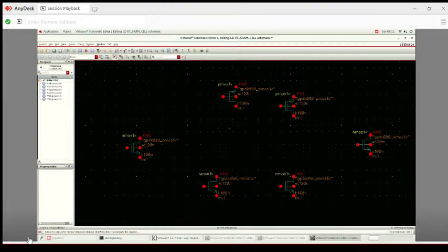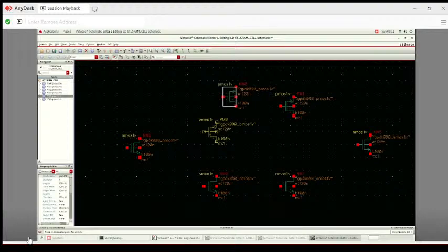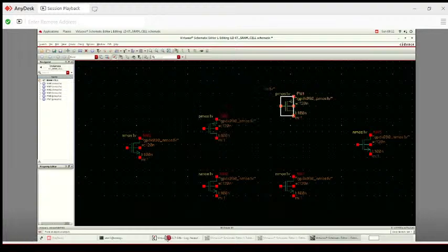So we zoomed in. As we can see, 2 PMOS, 2 NMOS. Let's align the PMOS with NMOS so we can make an inverter here, because a 6T SRAM cell is basically nothing but a combination of two inverters connected bistably, directly connected with each other. We can say it is a bistable latch. Okay, so let's design a bistable latch using the two inverters.